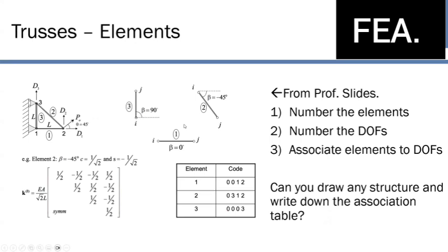So when it comes to truss elements, we've obviously covered this week with the professor. Just a quick refresher, we break down our truss system into elements. These elements join nodes. Based on the degrees of freedom, we can have different node numbers. We number these nodes based on the degrees of freedom of each individual one, and that is tied to how the part can move. So naturally, we look at here a roller. That's going to be restricted up and down, but left and right, it's free to move. This pin support can't move this way, it can't move that way. It's restricted in these two dimensions.